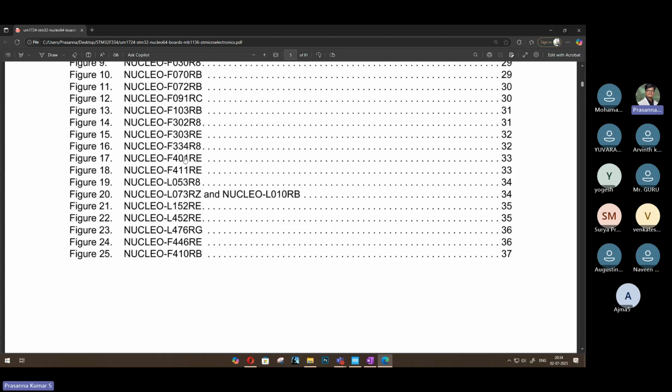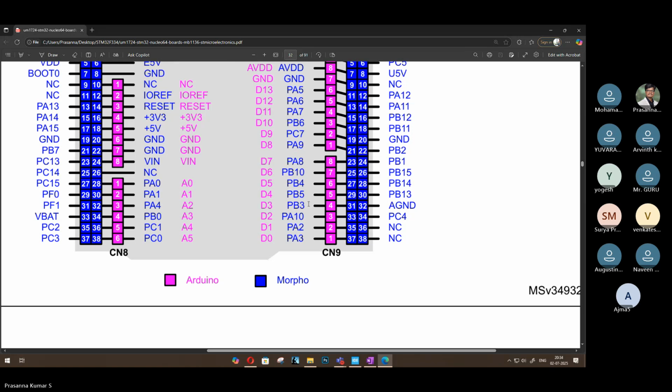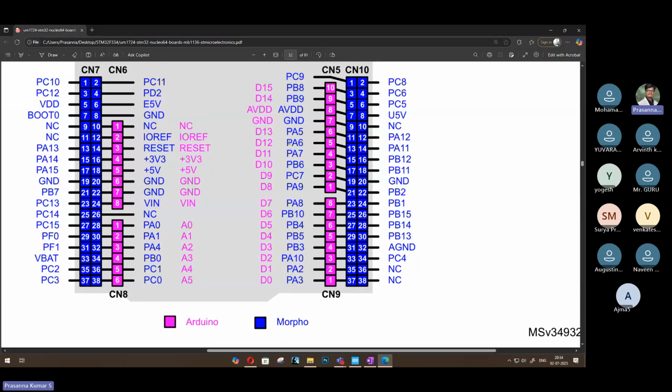So this is my 334 board. Okay, PS6 and PS7, these two pins, correct? Yeah, okay. So it is the 13th and 15th pin. That is 1, 2, 3, 4, 5, 6, 7th pin and the 8th pin I need to short. So left side 1, 2, 3, 4, 5, 6, 7th pin. And one more male to female.